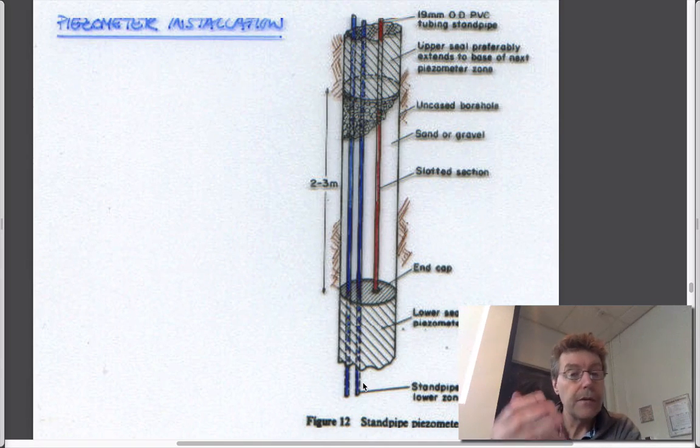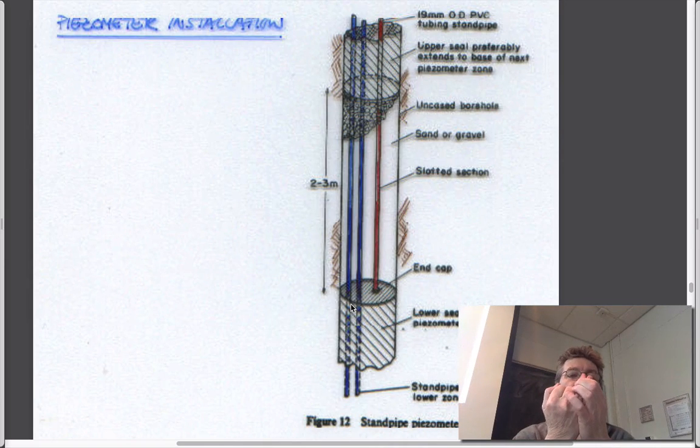So the way that you can get multiple zones within a single well is you go in, forget about these lower standpipes, you block the well with bentonite, so you can get these little pieces of pressed swelling clay which have lacquer on them, which are about the size of the tip of your pinky.